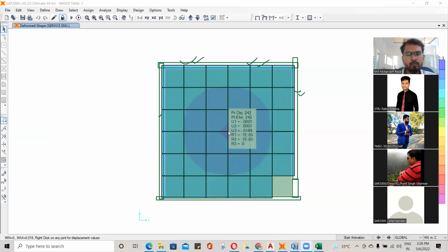How much is it? 18.4, correct, na? And check the nearby support. Which one is the nearby support? I was understanding it. This is the nearby support, na? How much? 15.9. This is the nearest support. 0.5 meter. Here is 16, 0.5 meter, 15.8 down. So this is the nearest support. And 1 meter above, 15.8. But this is going from the zero, it is going 1 meter above, I guess, na? 15.8. Just calculate. So you have to check the deflection with respect to the support.